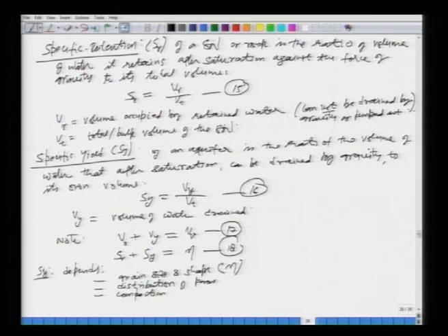You may have an undisturbed sample and you may have a compacted sample, their porosity will be different and their specific yield obviously would be different. So, you have the compaction of the stratum, right. Also the time of drainage. If we keep pumping water, the specific yield will be changing as a function of time, because the compaction characteristics may be different as a function of time.